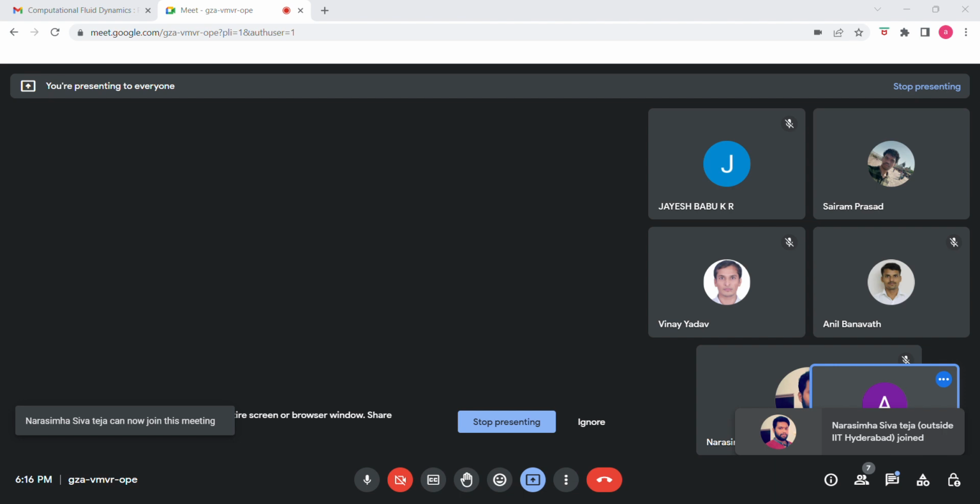And for the next option, it is given that dou square t by dou x square plus dou square t by dou y square is equal to 1000. Here q is given as constant, and the left hand side is similar to the first equation where q is equal to k d square t by dx square, where it was given that k is a constant. And so option 2 is admissible.